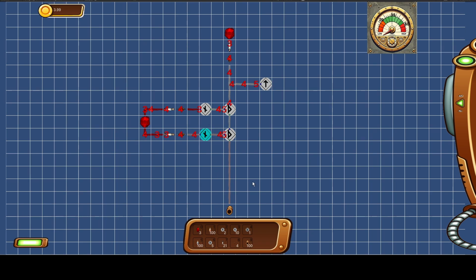And yeah, I've changed quite a bit how this thing does its power dissipation as well. Previously, when one of these numbers got to something that consumed it, it moved backwards through the chain and then distributed power appropriately for all of them. Now it actually does it as they move, which is, I think, more accurate. And it helps too because the fuse is up here, so you want this to blow before this blows. That's kind of its purpose. That is its one job. Blow when too much power goes through you. So that is an important thing for that element.